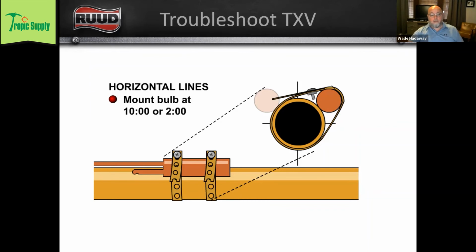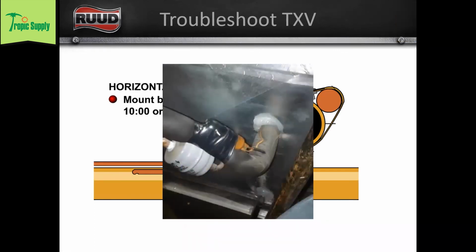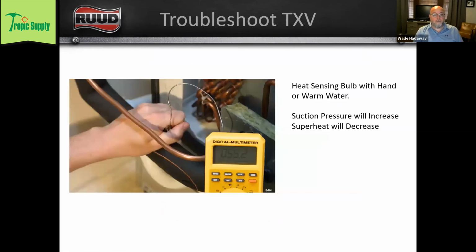And like I said, we used to have some coils that had expansion valves mounted inside the coil box, but I don't think we have any currently that are spec'd out that way. I think we had issues in the past where, when they were in the inside unit, they were left on and they were overheated when they were soldered. That is true. I've seen that many times. Yep.